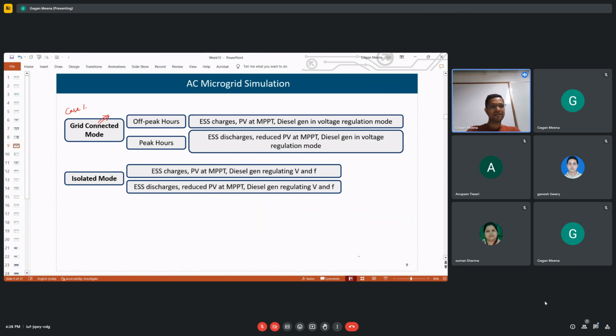But then why is the DG set not feeding at that time? Because the diesel generator output is less than load minus generation. If it is more than that, then the gap will be supplied by the diesel generator and it will also charge the battery. So P_L minus P_G will be supplied by the DG and the excess will be used to charge the battery. But if it is less than that difference, then it cannot supply the load.